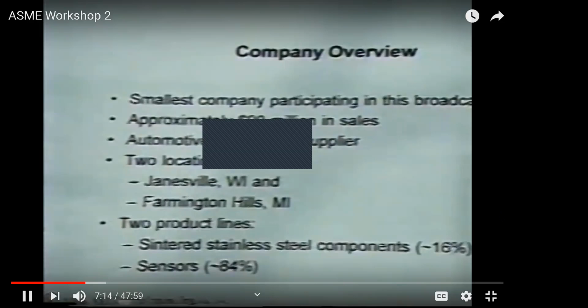So back in 1989, there were basically two types of pressure sensors being supplied to the automotive market in production. These were based on strain gauge technology and capacitive-based technology. Both of these are macro-based type sensors, that is, you can actually build these with your hands. You don't have to use photolithography to build these sensors. Both of these are still currently in use, although they are slowly being phased out in favor of some of the MEMS type sensors.